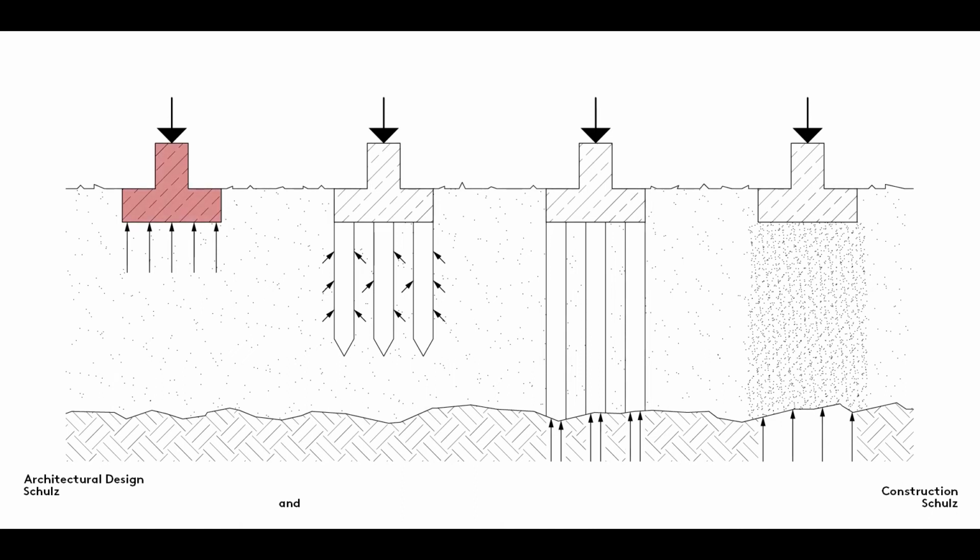In the case of a raft foundation, footings disperse the building loads to the ground over a large surface area. A system of footings in which a building is set on piles is referred to as a deep or pile foundation. These foundations achieve the necessary stability either by creating friction with the ground or by extending down deep to load-bearing strata. Load-bearing capacity can also be increased by improving the ground through soil replacement, laying a geotextile membrane, or injecting a stabilizing material, for example.